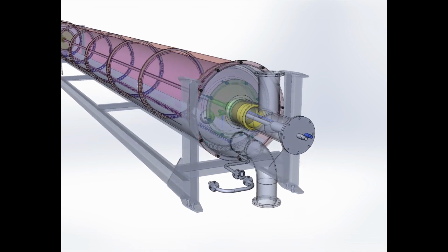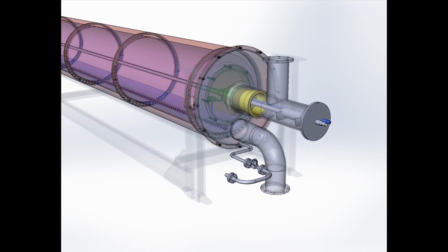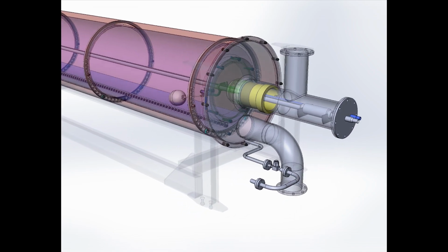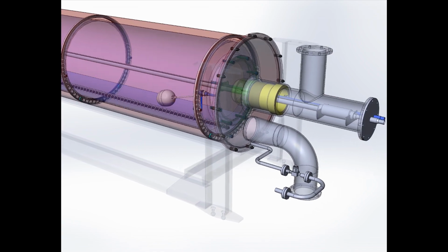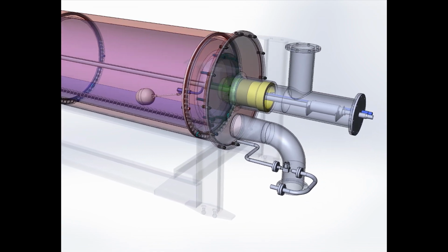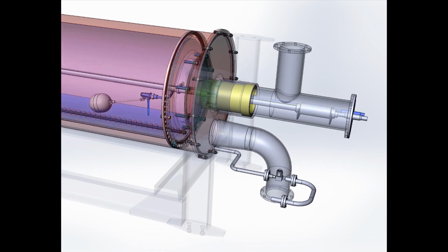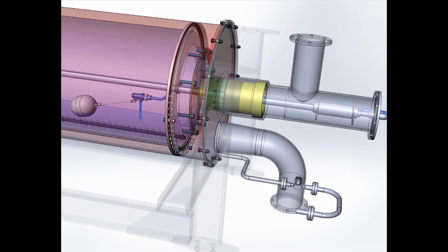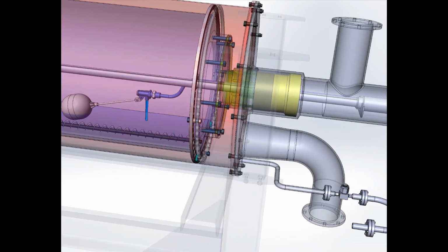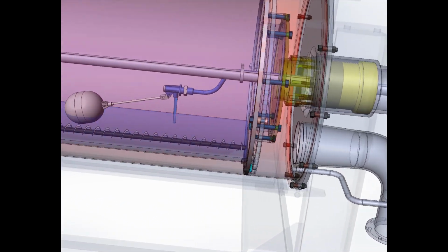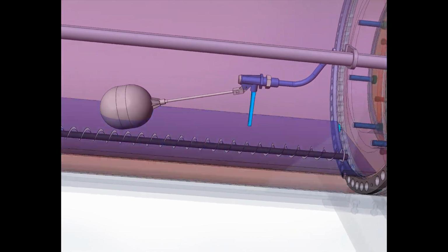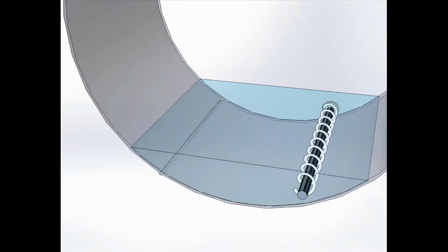The most important design element of film evaporation drums, which distinguishes them favorably from other evaporators, is a system of continuous mechanical cleaning of the heating surface when concentrating scale-forming solutions. This system is quite simple and in the design under consideration consists of a thin metal strip twisted into a spiral, rolling under the liquid level inside a rotating drum under its own weight.